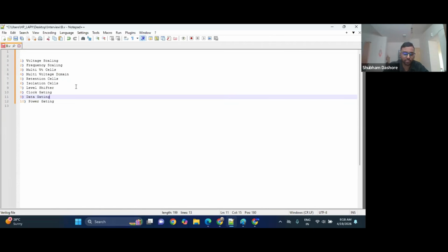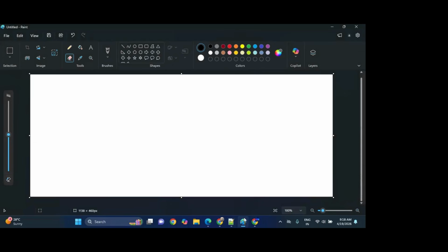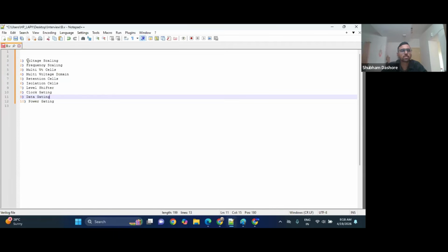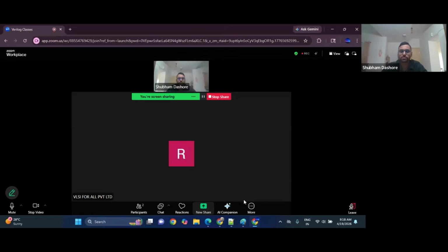I understood the functionality, identified and resolved some critical functional issues, and enabled early release of the RTL for the DCVS block. In the DCVS block, the low power techniques used were voltage scaling and frequency scaling.